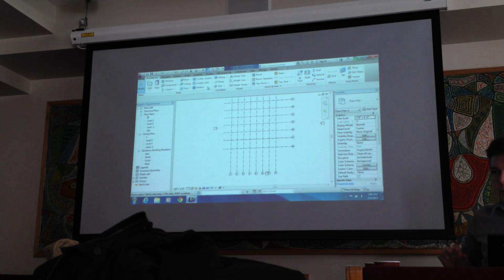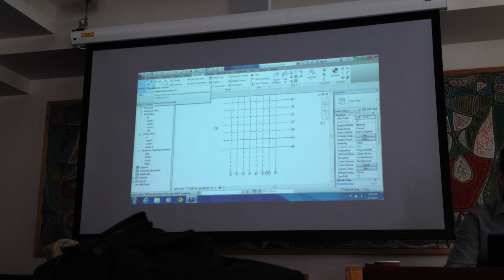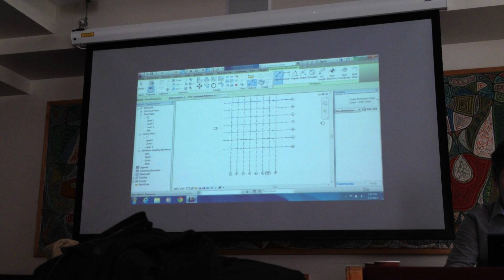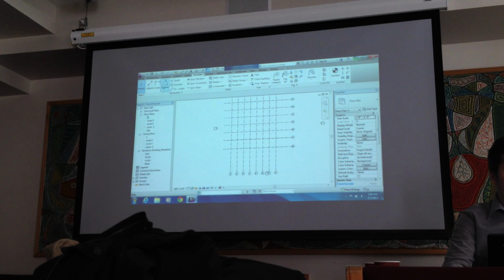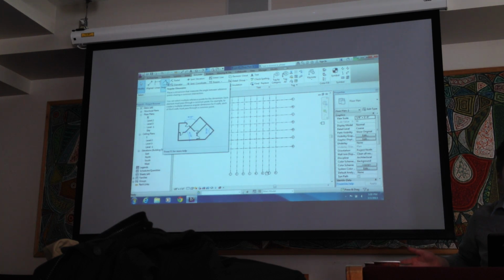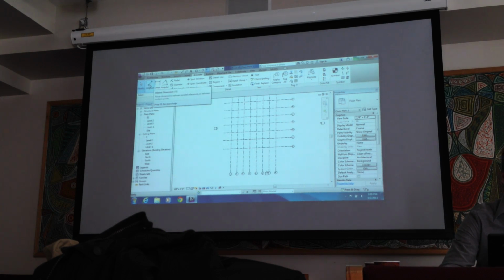If you want to be really quick for this, there's a second way where you don't have to align it properly. So if you wanted yours to be all at the same increments, nicely, you can click Annotate, and you'll see there are different dimension tools that you can use. So, back to Annotate. There's aligned dimensions and linear dimensions and angular ones. These are the main ones that you're going to be using. Angular is obviously for angled wall structures, so if you want to get a precise degree, or you can use the aligned dimension for straight lines.